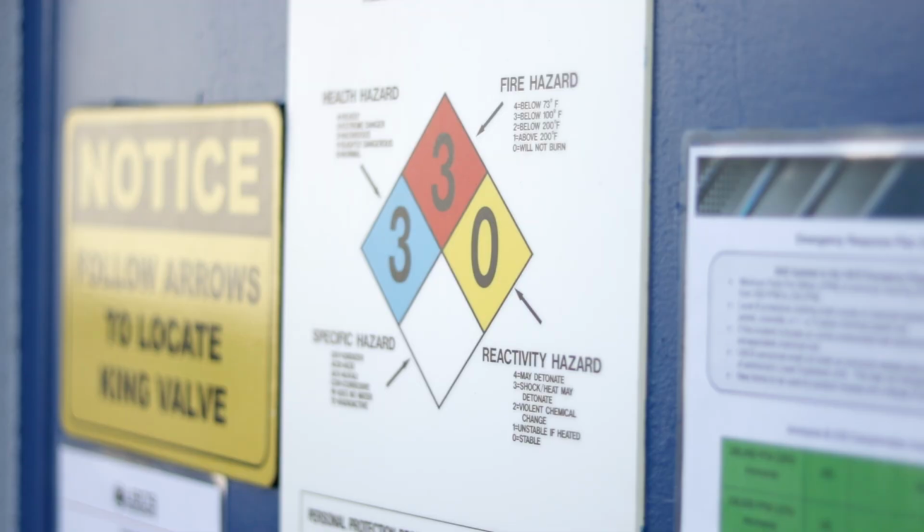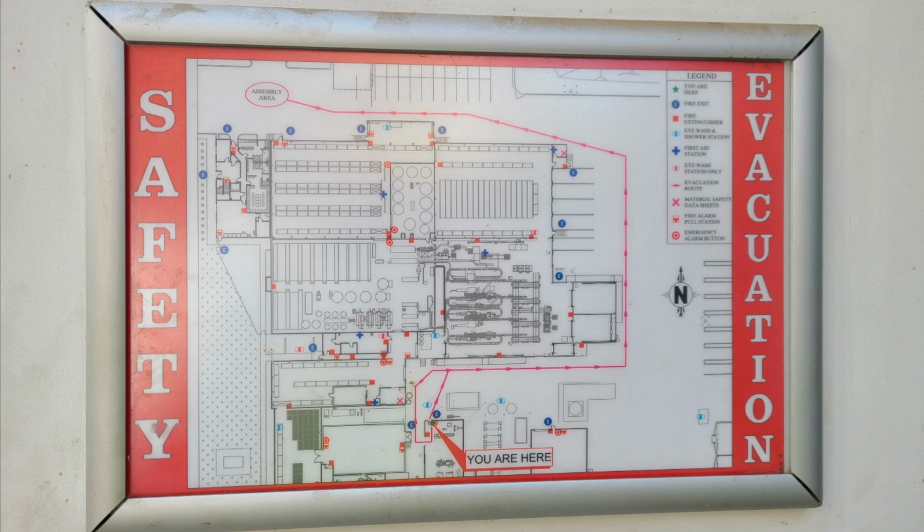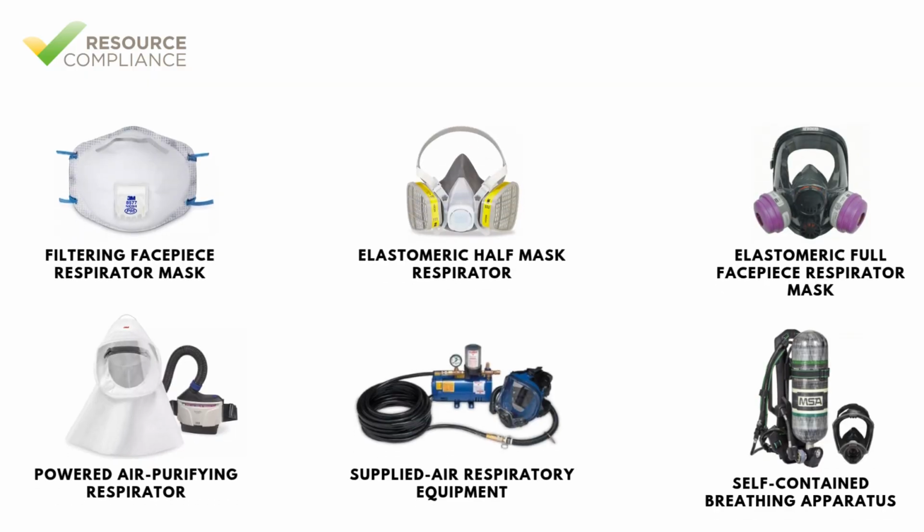Refrigerants have the potential to create dangerous atmospheres, either toxic, corrosive, or oxygen displacing if a leak occurs. Respiratory protection awareness is critical to protect health and ensure technicians can safely respond or evacuate during emergencies. There are several different categories of respiratory protection that a refrigeration professional should be aware of.